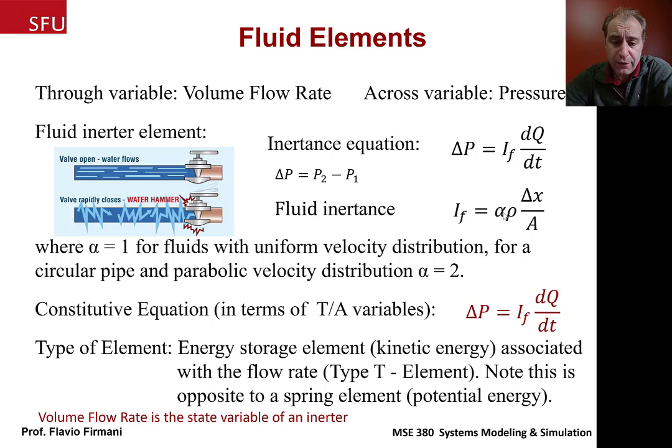So the constitutive equation that we're going to use is this one, where the difference in pressure is equal to the fluid inertance times the time derivative of the volume flow rate. Sometimes I'm just going to refer to flow rate to shorten that. Now, this is going to be an energy storage element. There is kinetic energy associated with this element.